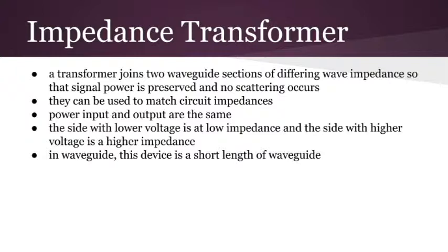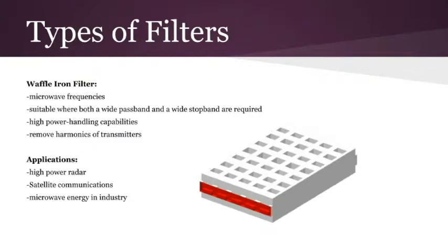Impedance matching is basically how a reflected wave is created. The reflected wave is added to the incoming waves, creating a standing wave. So impedance matching is very important in the waveguide filter. And transformers can be used to improve selectivity of resonant circuits. Impedance transformer circuits present the resonant circuit with a source or load resistance that is much larger than what it actually is. There are many types of waveguide filters for the outstanding number of applications in the real world.